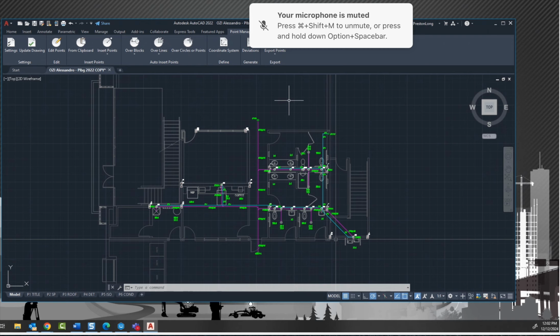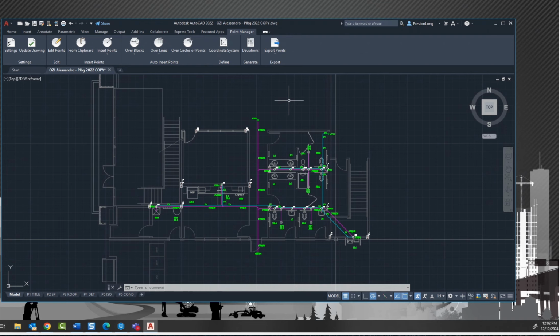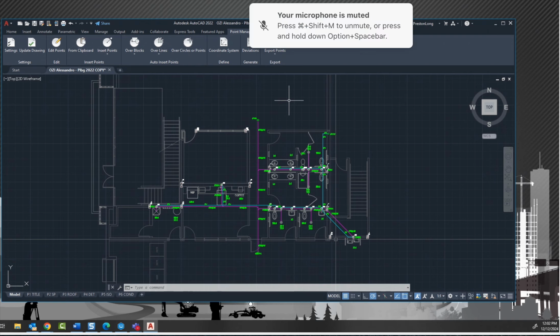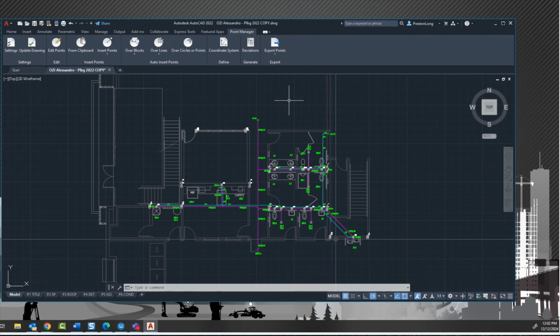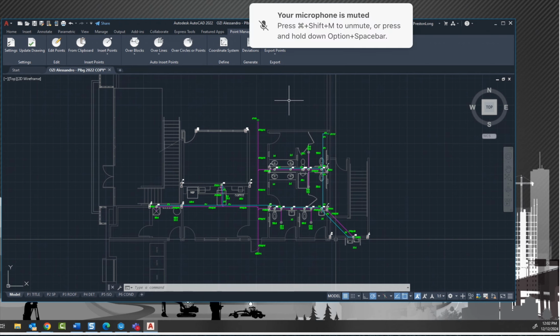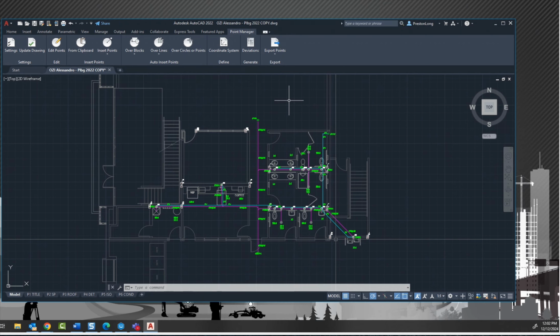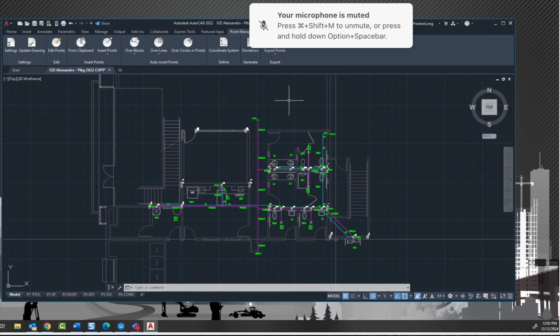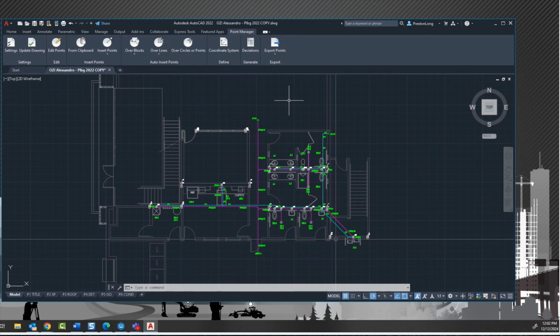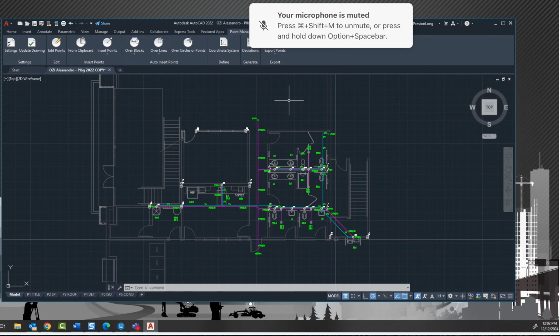But you can place all that stuff in here. You can draw the grid lines in here that you want to use. If they don't have them in here, if there's a 4 foot offset and you want to use the grid line setup routine, you can draw whatever you want in here, just so that when it comes over to the data collector, you're matching points in the field with objects in the file, and you should be ready to go, if that makes sense.